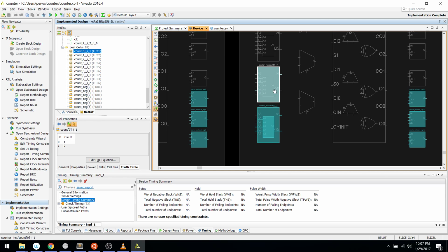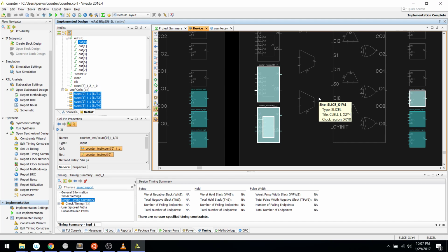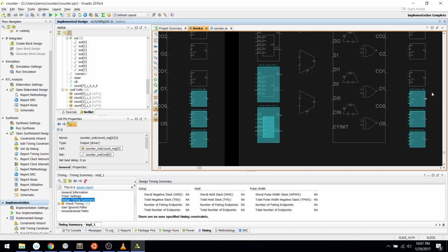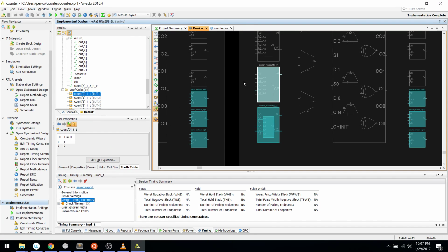You can also select this input pin. You can see the populated input pin is highlighted. If you select this manually and do Control-T, first it selects the net, because it's the pin, then the net, and then whatever is connected to the net. So in this case, it actually does the right thing. If I look at this Q, it's a little hard to see. But you'll have to trust me that even though they don't visualize it very well, this internal block connectivity is actually there. The output of this goes to this, and the Q in this goes to that.